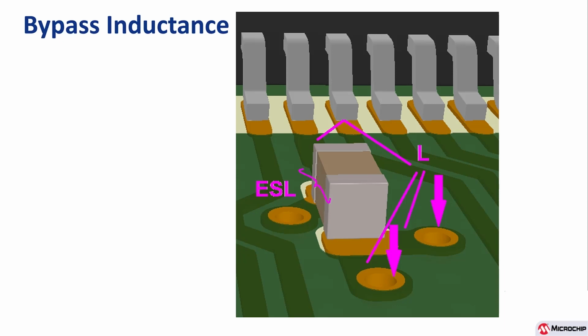That's good. It's got two vias on the ground. Remember, those are return, but we're going to call it ground, which divides that inductance by half. So it improves that, and it also increases the capacitance of those vias by 2. So that's great. There's only one thing that I would do a little bit differently in this illustration to make it a little more perfect. That right-hand ground via would be put to the left so that the ground loop area between the power and the ground via would be shorter.